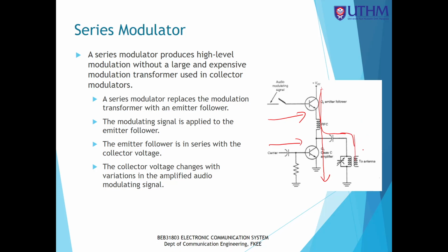If you see from here, if the voltage at the base is more than the transistor threshold, what happens is that the current can flow from VCC to ground, and it will also charge the LC tank circuit.